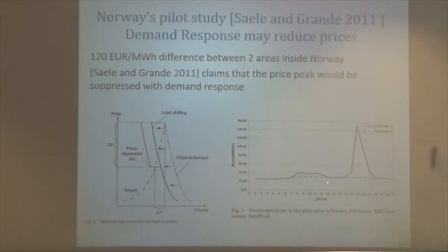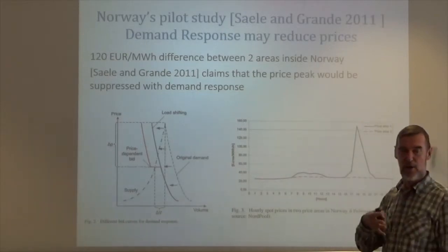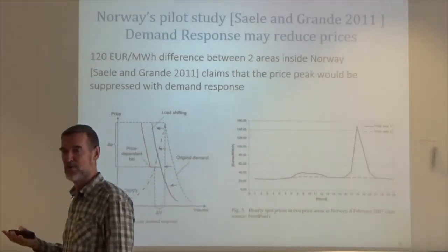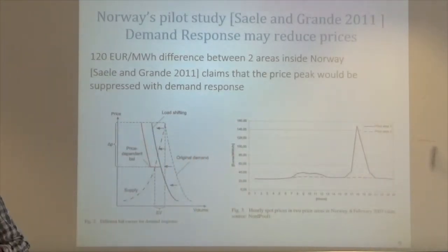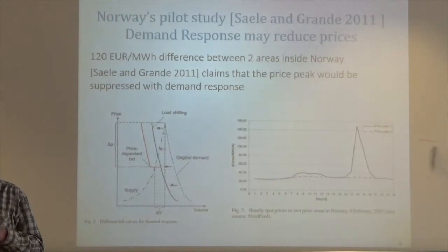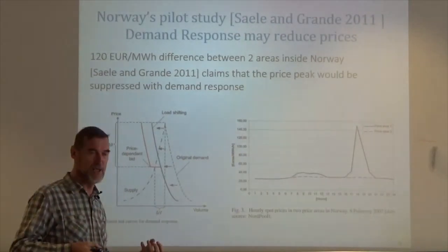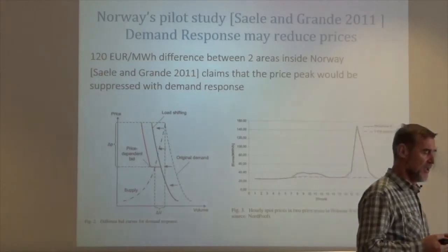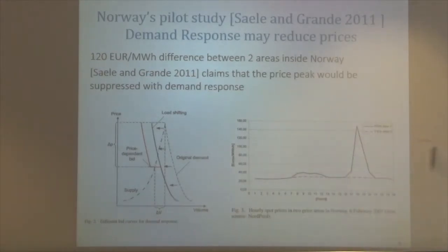And the prices of electricity, when they become very variable, they follow the Lagrange multipliers of a DC approximation of the power flows. And we have seen what can happen if you have congestion on a line. All of a sudden, the prices at one place may become very expensive. On the other side, prices might even become negative. That means you are paid to consume.